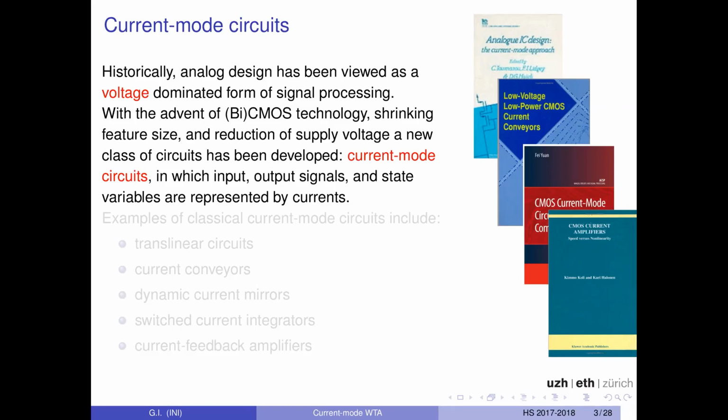So you can imagine that with such a small power supply, where 0 is the minimum and VDD is the maximum, and with such a small range, it's more and more difficult to implement analog circuits that can actually work reliably. That's why, already when power supply voltages were around 3.3 and 1.8, current mode circuits started to become more popular.